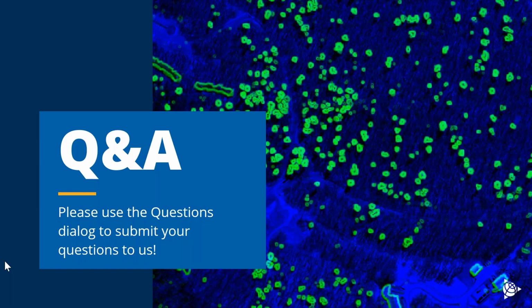Some of those points were probably ground, but other points were actually hitting mid-height 3D objects. I did that because coniferous species, specifically the hemlock tree, have lower branches that would be picked up from that pulse return. Making a slope layer from those last returns essentially made an edge layer that I could use to make the initial candidate objects at the very beginning of my rule set.